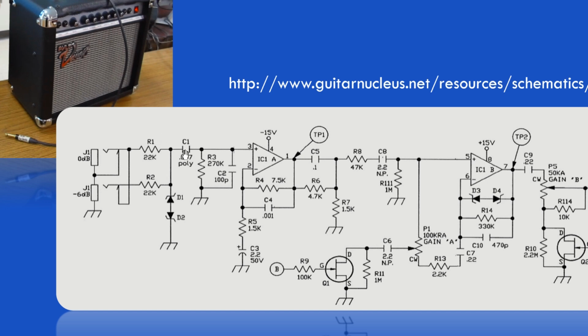And we discussed how C1 is a DC block to prevent any DC that might happen to be on here. There shouldn't be, but if there was, to prevent that from going into the next stage, which is this op-amp circuit. But along the way, there is a capacitor to ground. So if you look at R1 and that capacitor to ground, what does that look like? It looks like a low-pass filter.